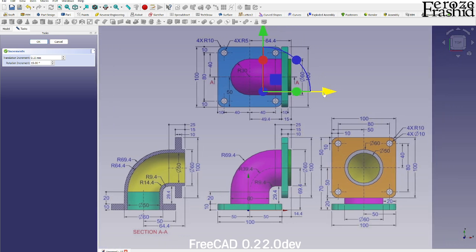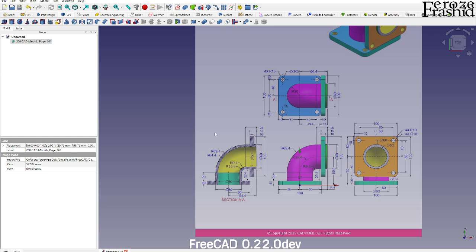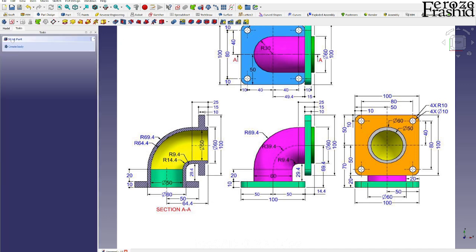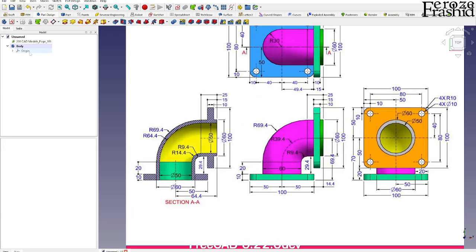So I want to draw a profile of this bending profile, so to speak, and then I'll be lofting it over. This model per design is a bit easier to handle, so I'll do it in the Part Design workbench. This workbench arrangement gives away the fact that I'm doing this model in the FreeCAD 0.22 developers version.